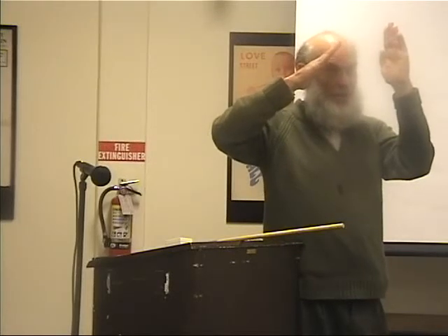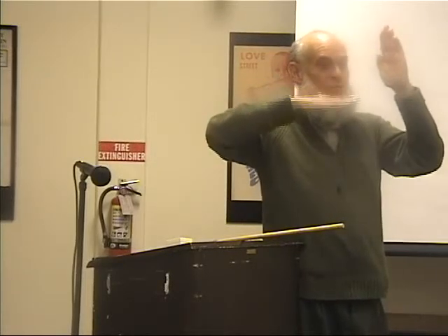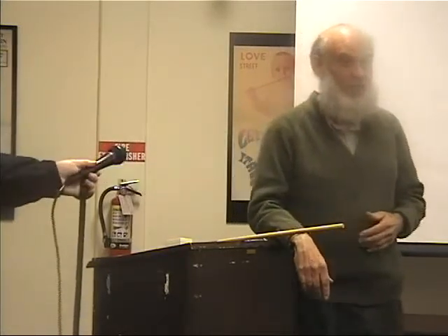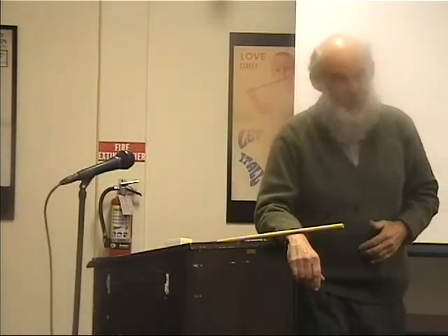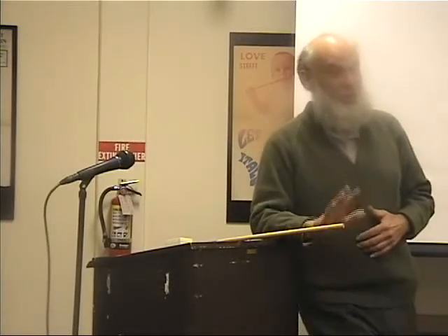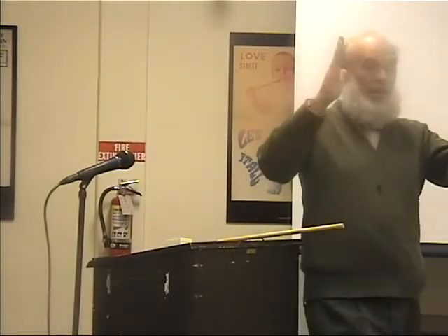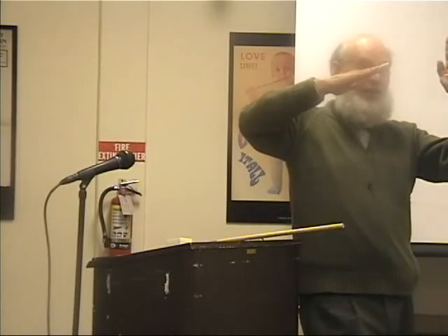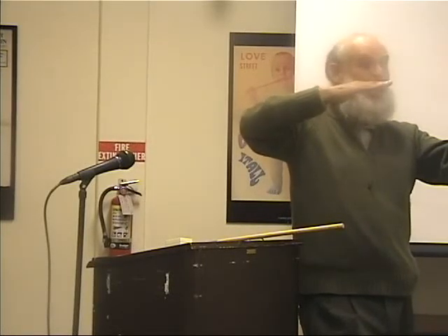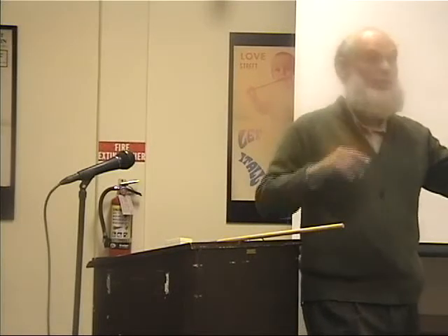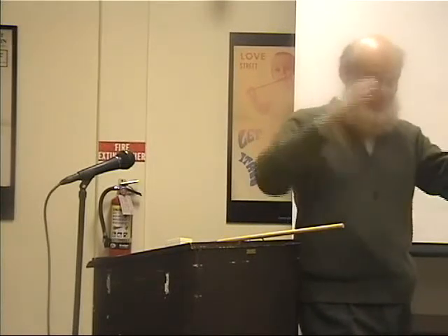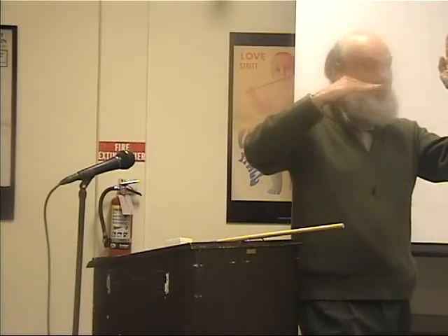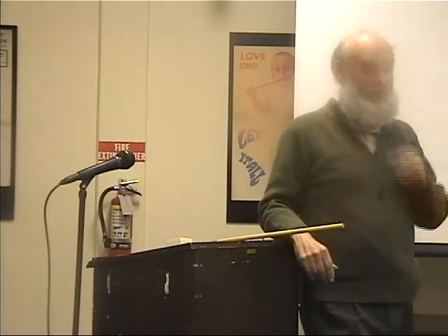Now if you get to the situation where the line is 1/4 wavelength long, a wavelength at 60 cycles is 2,880 miles. So it's kind of hard to do, but there are some power lines that are very long. So here's what has to be done. If the line gets longer, the generator at the other end becomes more and more out of step with what it thinks is happening because of the retarded potential. When they become 90 degrees apart, they can no longer stay synchronized and you get a big blast.